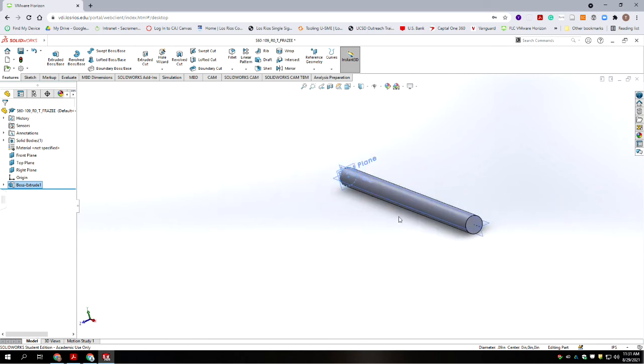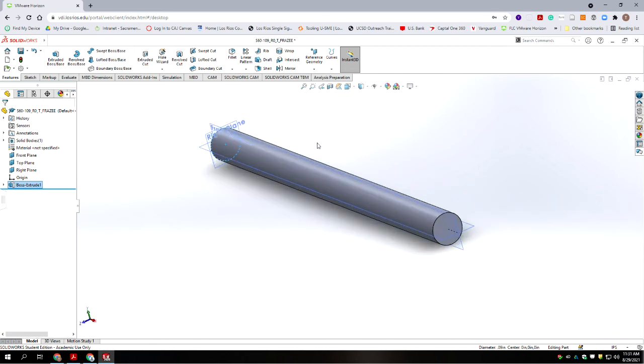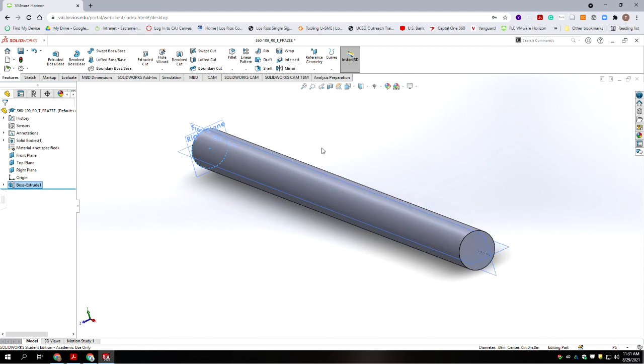You have now made your first solid model using the extrude command, and it moves the planes to be the size of the part. And now you've done that, you can go back and select on them and hide those planes. It's up to you. When you start later on, you'll see when we start doing assemblies, the planes can become a distraction.